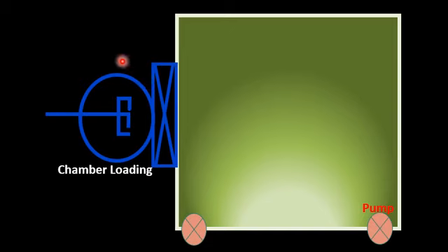So due to this, the chamber loading setup in the molecular beam epitaxy is load locked, and the flipping ring is used between the chamber loading setup and the molecular beam epitaxy reaction chamber. With that ring, it flips and turns, and the precursor which is present in the chamber loading setup is introduced inside the reaction chamber, and they don't break the high vacuum, and the molecular beam epitaxy becomes more realistic.